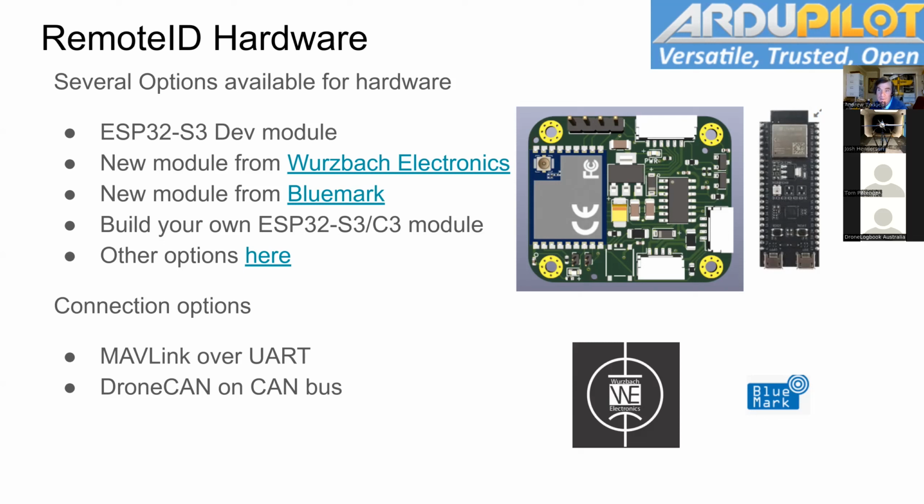I know some of the ArduPilot partners have custom ground station interfaces. They run their own code. All you need to do is fill in the right MAVLink messages and send them. And as long as you're giving a good 1 Hertz operator position from a decent GPS, then you're good to go.